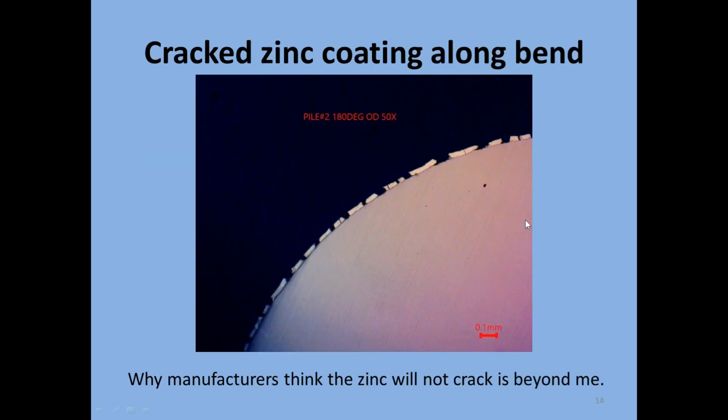Okay? And there's a metallograph of a cross section of that bend, so you can see that when you bend galvanized steel, it will crack that protective zinc coating, and your corrosion will occur even faster at those areas. So a lot of people have the opinion that galvanized steel will survive forever and anywhere, and it's not necessarily true.